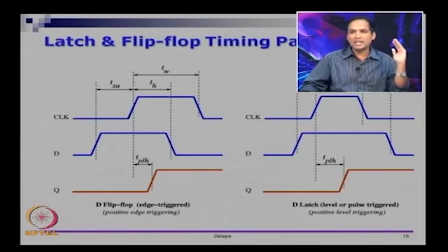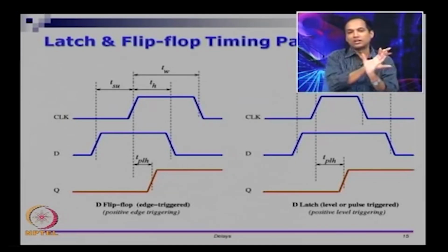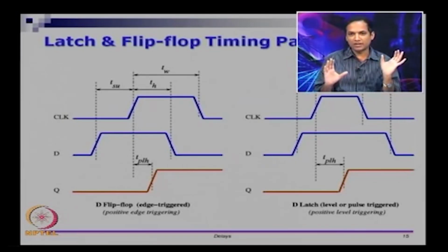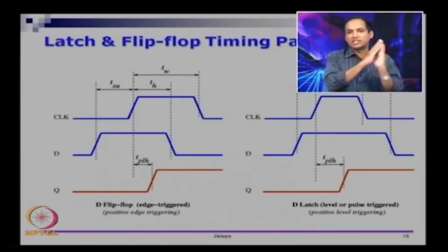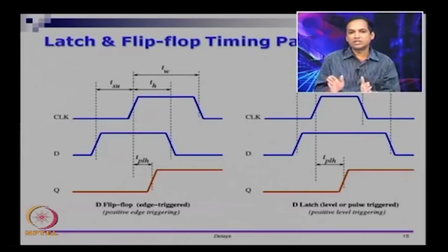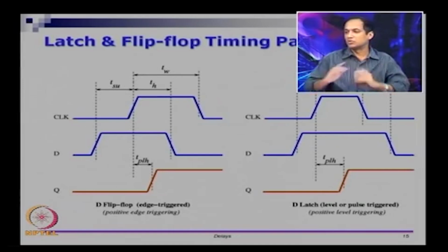So, the opening and the closing edge of a flip flop is actually the rising edge of the flip flop itself. You go and look at that edge, it opens the flip flop for the output to copy from the input, but it also closes. Once the rising edge is gone, then changes in the inputs are not going to translate to changes in the output, right. So, this is the notion for an opening and closing edge.